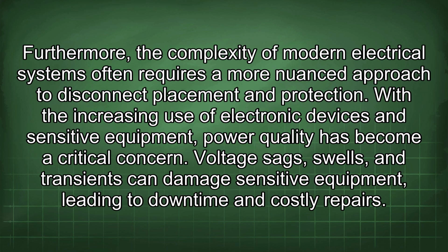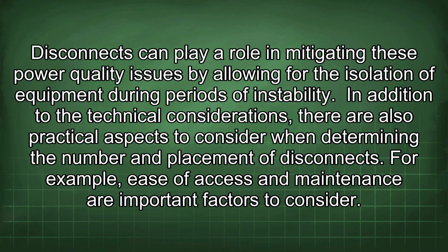Furthermore, the complexity of modern electrical systems often requires a more nuanced approach to disconnect placement and protection. With the increasing use of electronic devices and sensitive equipment, power quality has become a critical concern. Voltage sags, swells, and transients can damage sensitive equipment, leading to downtime and costly repairs. Disconnects can play a role in mitigating these power quality issues by allowing for the isolation of equipment during periods of instability.